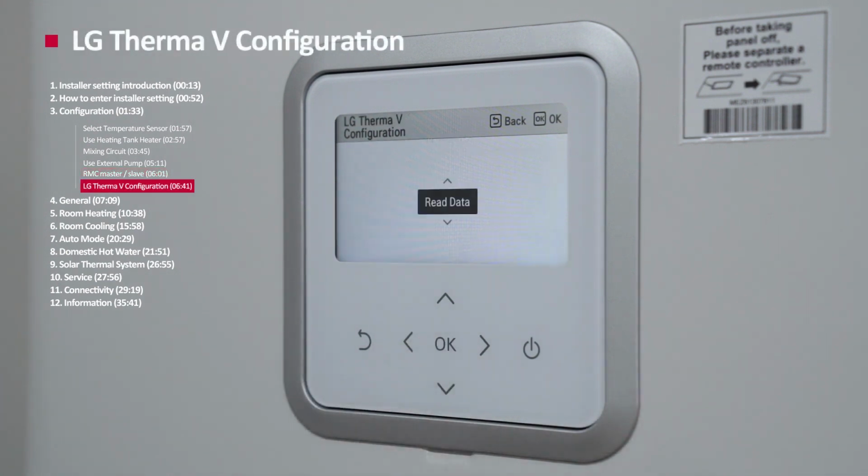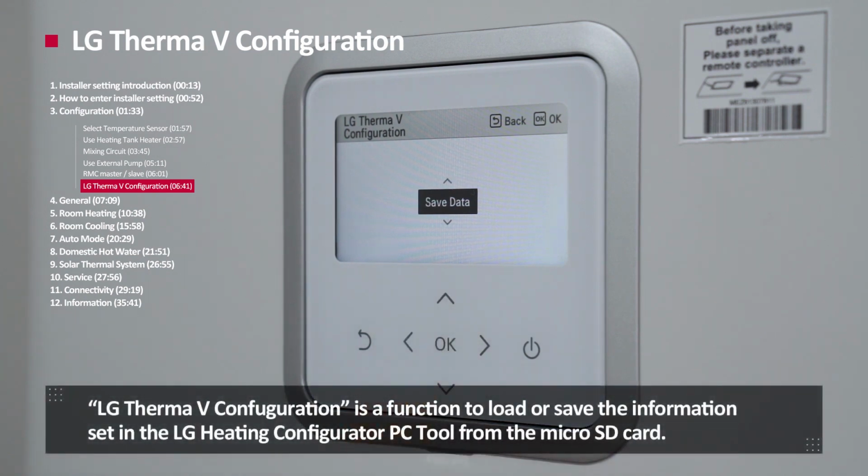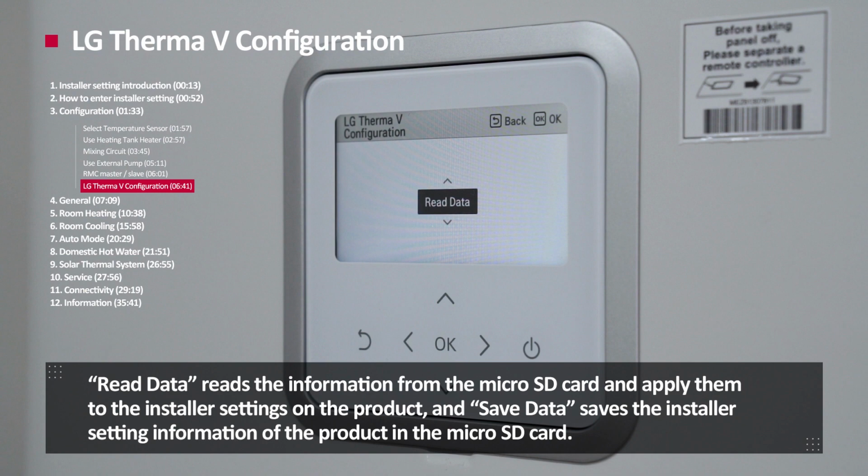master remote controller is overridden, and the air temperature sensor on the slave remote controller is used for control parameter. LG Therma V configuration. LG Therma V configuration is a function to load or save the information set in the LG Heating Configurator PC tool from the micro SD card. Read data reads the information from the micro SD card and apply them to the installer settings on the product. And save data saves the installer setting information of the product in the micro SD card.